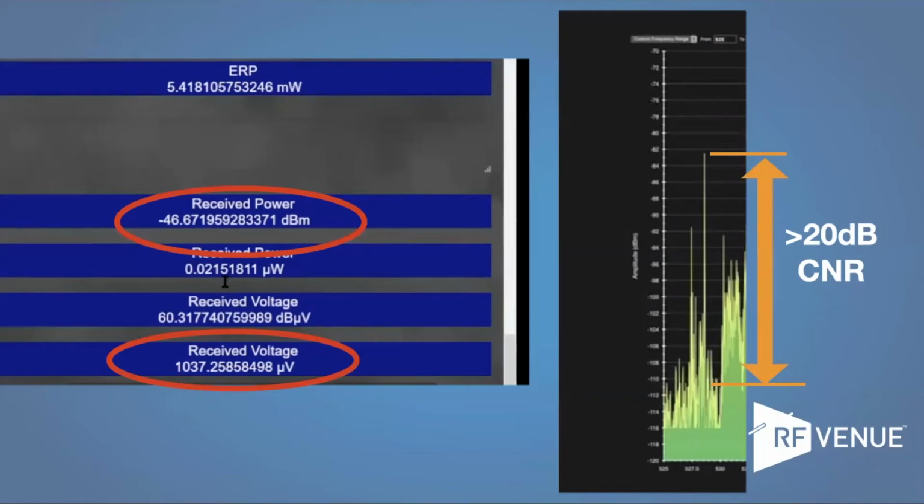Modern receivers are darn good, so you probably don't have to worry about that at all. But then there's a noise floor, and realize this is moving. That's not standing still. So where that floor actually is, you kind of eyeball however you feel comfortable in doing it. And if you were to look on a scanner, what this number that you see better be at least 20 dB stronger than that noise floor.